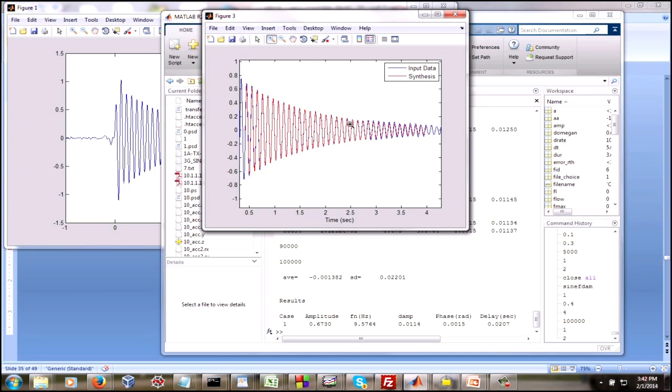And one thing we have to also take into account too is that the Pegasus drop transient is not a perfect textbook event, and there's always possibilities of some nonlinearities and even some higher modal behavior that's entering in. But for the most part, we got a very good curve fit. So this is telling us that the Pegasus drop transient has a natural frequency of 9.57 hertz, at least for this mission, if we truncate the last 2 digits.